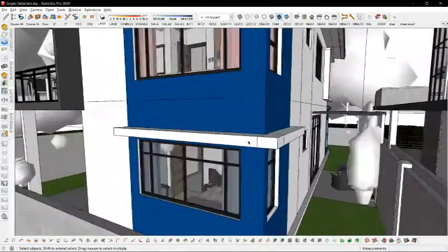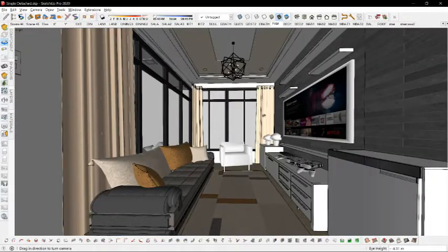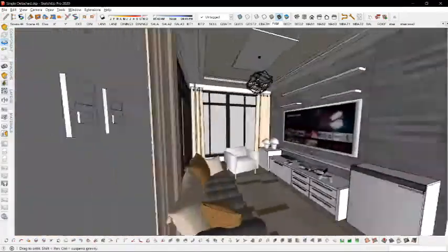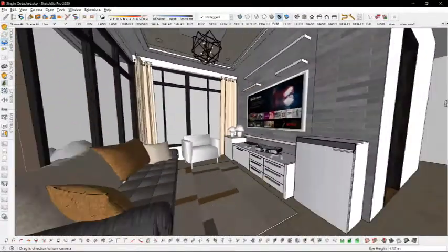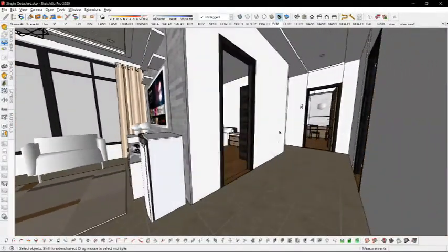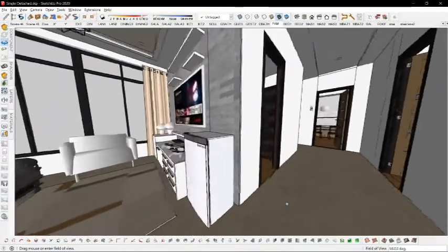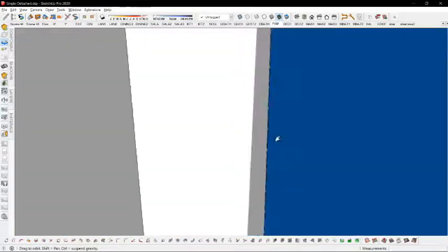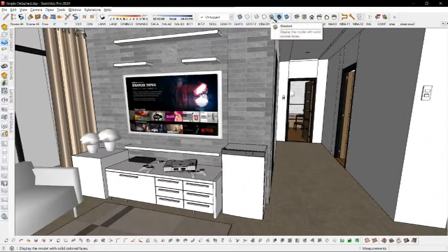For example, just trying to look around, press the letter L instead of having to rotate every now and then and makes everyone dizzy. So L. Same is true for the field of view. Ctrl-Shift-F. There. And if you want to speed up some modeling, you can turn off the textures by going to Views and Shaded.